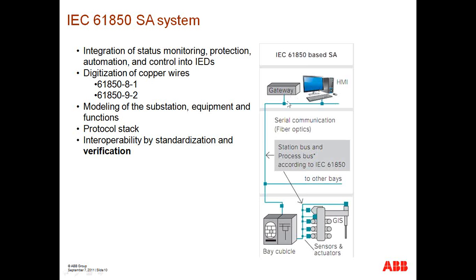So when we look at this picture, in this part we have the substation with the gateway, the HMI, and the relays. Here we have the bay cubicle inside of the substation. And then here inside of the switchgear, you're going to have a network, or your process bus network, that is gathering, or making the connection of, those sampled measured values.